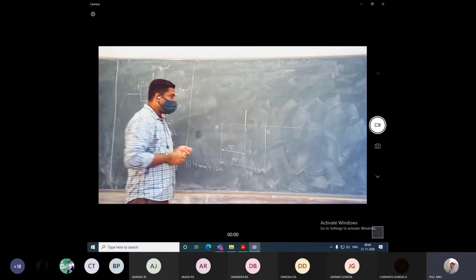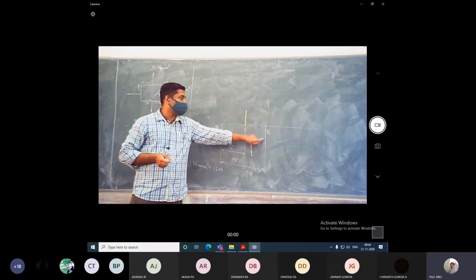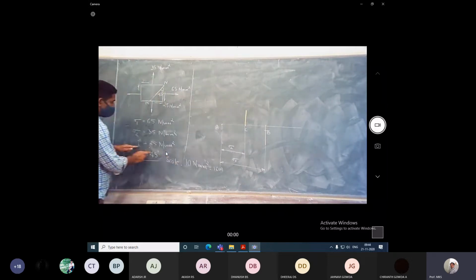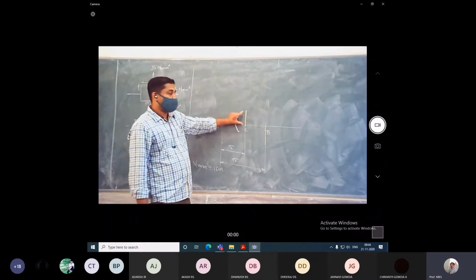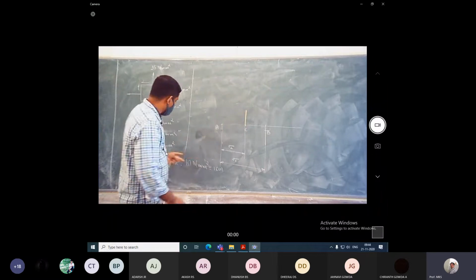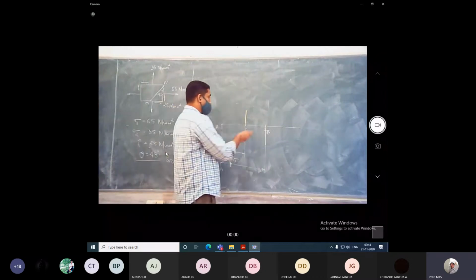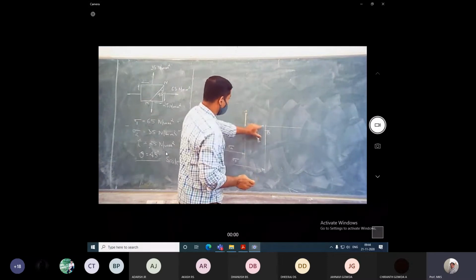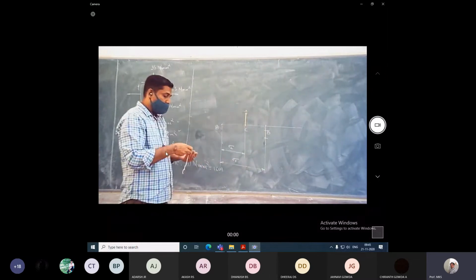Next, after drawing the perpendicular downwards at point B and above the line at point C, there is one more data, the shear stress. For the shear stress, with a suitable scale, cut the arc on the verticals we have drawn. For my scale, 25 is 2.5 centimeters. Measure 2.5 and cut the arc for both the verticals we have drawn.